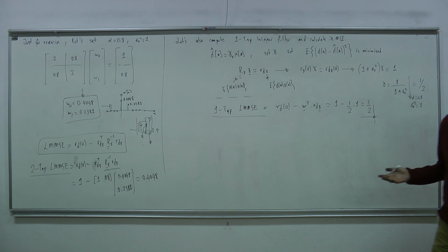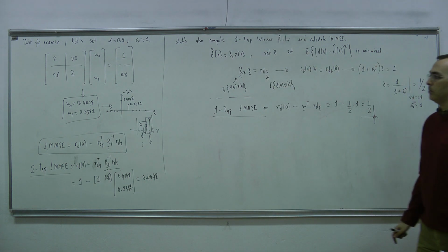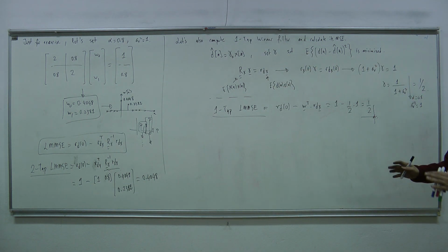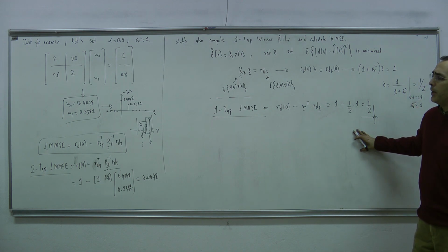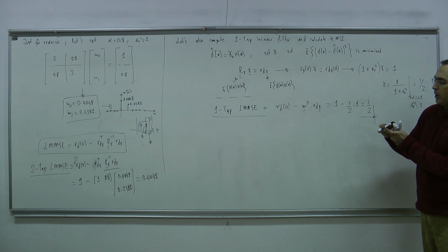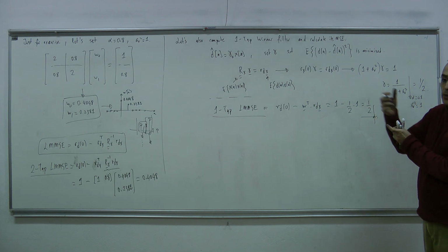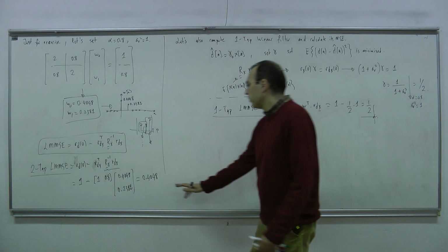Now the next question is, how about a 50-tap filter, 60-tap filter, and so on? So where should I stop? What is the limit of this? Later we will calculate infinite impulse response filters, IIR filters, and you can get a number for the IIR filter. So in practice, if you are very close in terms of linear MMSE to the performance of an IIR filter, then you stop, isn't it? Because it isn't worth any more computation. Okay, so that is it.